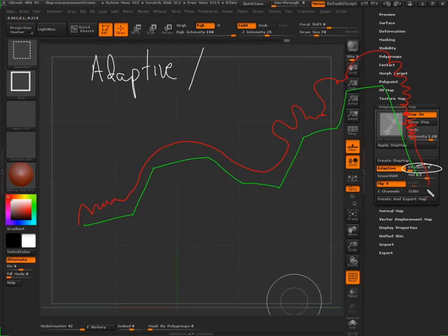If you do not have adaptive on, well, actually before I get there, the way displacement maps work is that they'll take each one of these faces and each one of these vertices. In terms of a bare bones representation, what a displacement map does is it calculates out a ray from a vertice and says, hey, you are X units away from me.